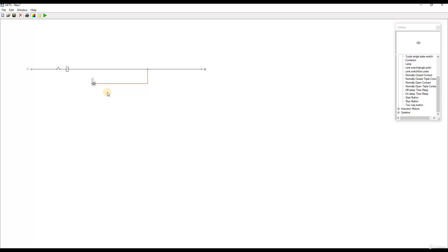And also, I'm going to add the normally open contact, right? If I go to normally open contact, double click, put it like this, and then connect these two, and then I'm going to connect to the phase. Okay, so what do we have now? The moment I press this button, this relay will latch, this will close. If this closes, what's going to happen is the power will flow from the phase to the lamp to the neutral. But there is one missing thing.